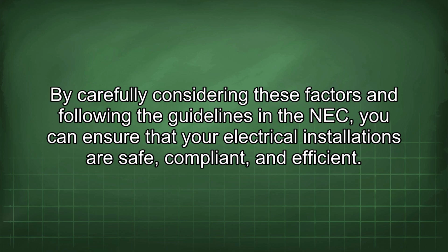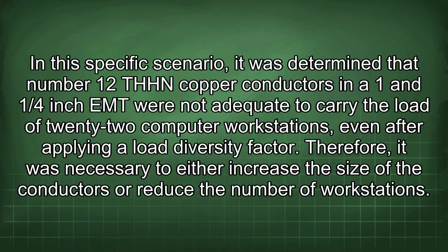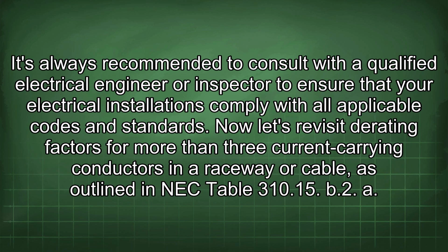safe, compliant, and efficient. In this specific scenario, it was determined that number 12 THHN copper conductors in a 1 and 1/4 inch EMT were not adequate to carry the load of 22 computer workstations, even after applying a load diversity factor. Therefore, it was necessary to either increase the size of the conductors or reduce the number of workstations. It's always recommended to consult with a qualified electrical engineer or inspector to ensure that your electrical installations comply with all applicable codes and standards.